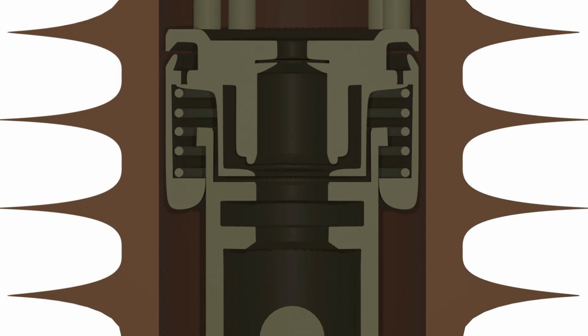With no arc, no further heat is produced, so the oil no longer generates gas. The remaining gas from the previous current cycle quickly passes through the vent and fresh cold oil flows in to take its place. As the moving contacts travel further downward after arc extinction, the lower oil vent opens. This provides a cleared path for the oil to flow upward and fill the gap between the contacts, restoring dielectric strength. The high dielectric strength of this fresh oil prevents arc restriking, ensuring the current is fully interrupted.